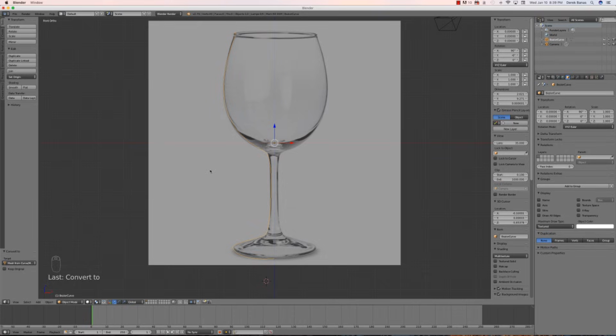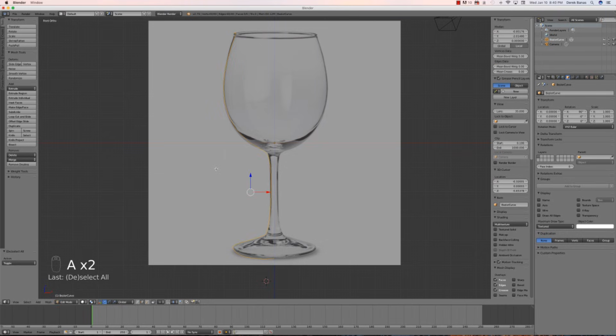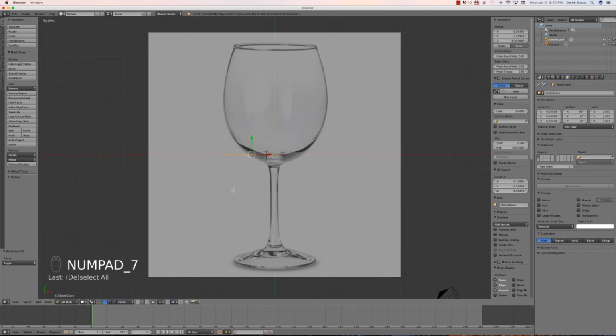Now I'm going to go back into edit mode with tab, select everything. Then I'm going to go E for extrude, and I'm going to create an extrusion, so it's going to become a three-dimensional shape. Okay, so there that is. I'm just going to move it in a little bit, left to set it. Then I want to do a select all. Make sure I have everything selected. Now I'm going to switch back into the top view, so I'm going to press 7 to do that.